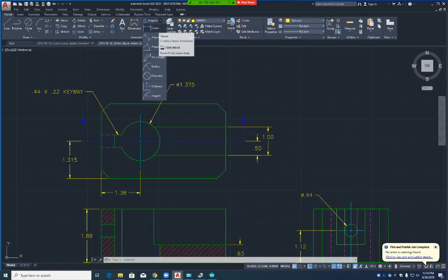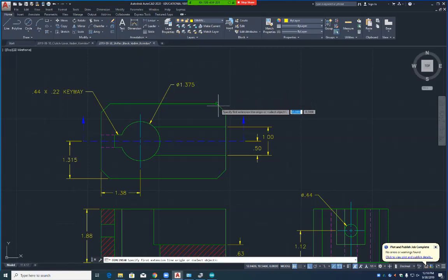Look right here, it says fillets and rounds. We could add another note in here and put all chamfers unless otherwise noted also on here. And then we wouldn't have to dimension that. But it's more visible on the drawing with an actual dimension. I'm saying technically we could get away with it if we had to, if we wanted to.